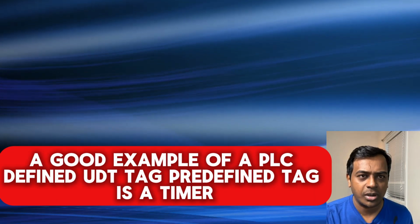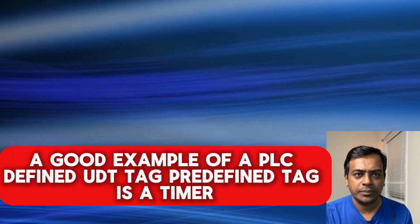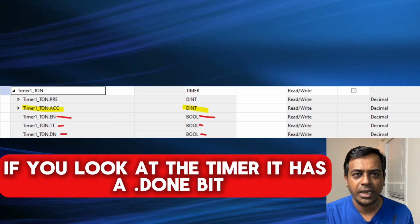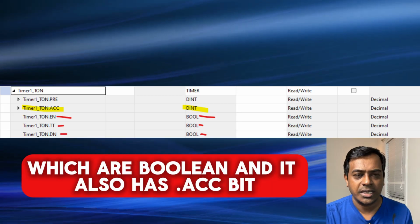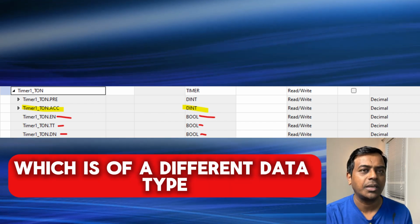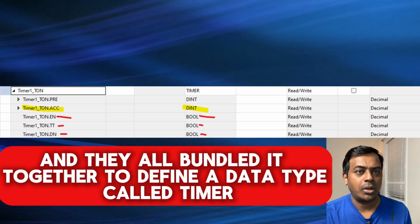A good example of a predefined tag is a timer. If you look at the timer, it has a .done bit and .enable bit, which are Boolean, and it also has .acc, which is the accumulator value, which is of DINT, a different data type, and they are all bundled together to define a data type called timer.